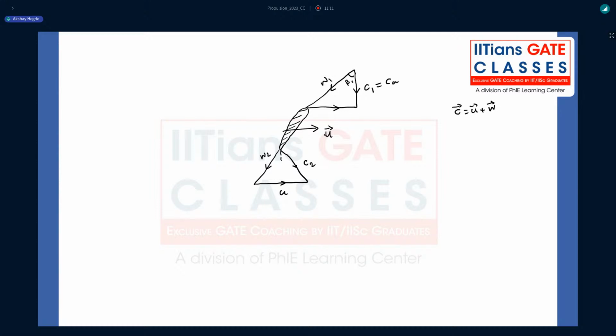Again, we are assuming the axial component of velocity remains constant. That's the assumption we are going to take. With respect to CA, the absolute velocity vector is making alpha 2 and the relative velocity vector is making beta 2. Right. So now our velocity triangle is with us, and we can easily proceed with the problem.